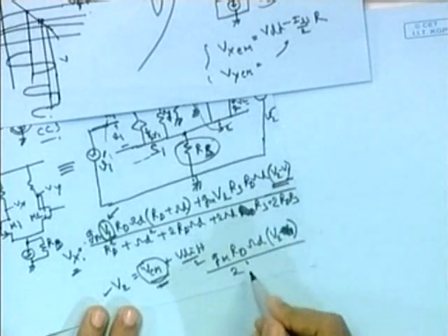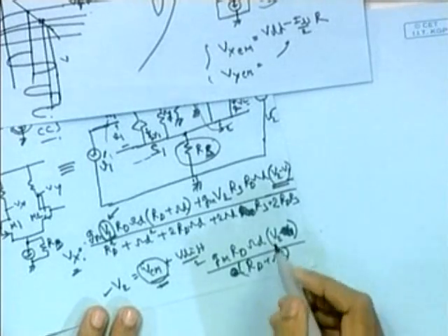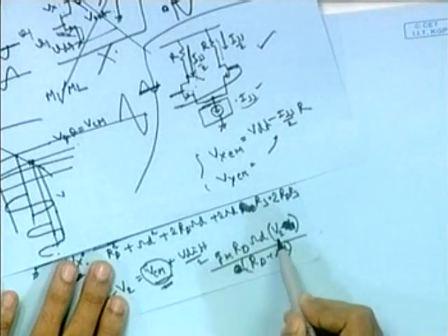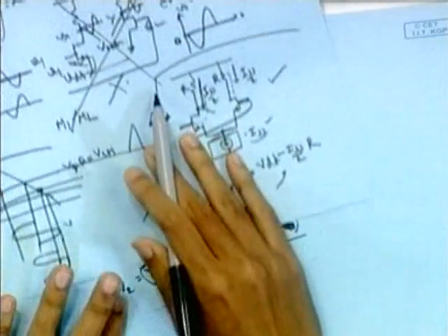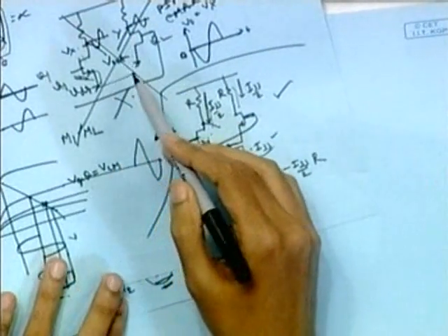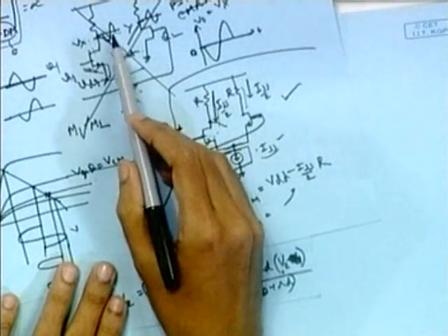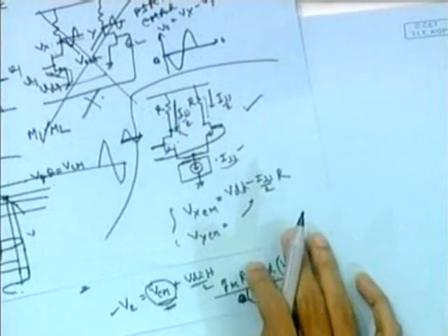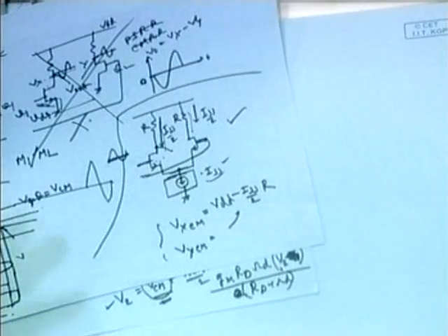We will get this one with RS 0. So you see that with RS 0 only V2 term remains here, and that V2 is a function of VCM. So we are going back to this circuit, and the output of this circuit contains the input CM level. So the effect of finite resistance is that our input common mode signal is getting amplified or attenuated at the output.